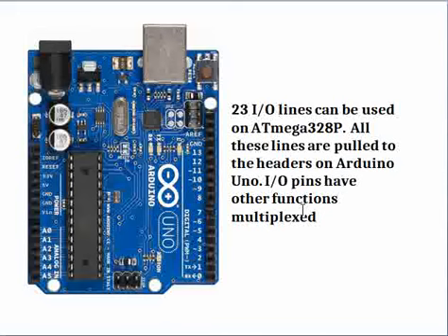So ultimately, even though the 23 IO lines have been claimed, if you are using the Arduino board for some other interfacing, then you cannot use all the 23 GPIOs. Even if you take any microcontroller, that's basically a marketing strategy where they claim the IO pins, but ultimately if you use it in an application, it comes down to a very low count.